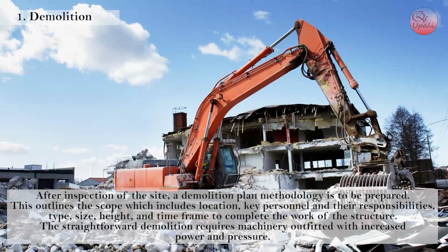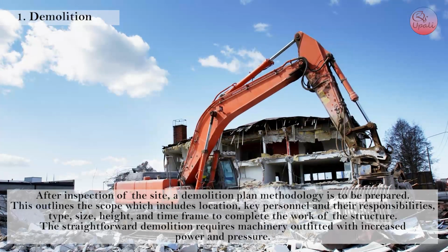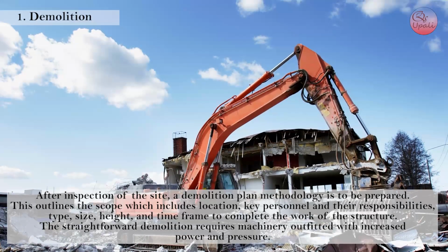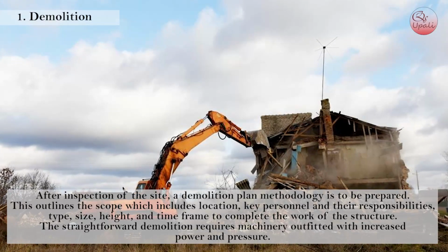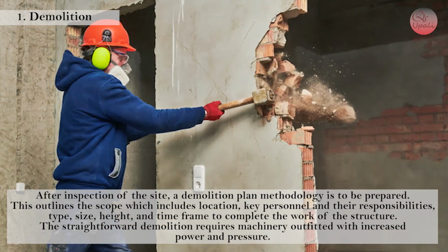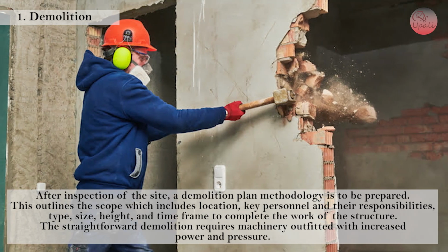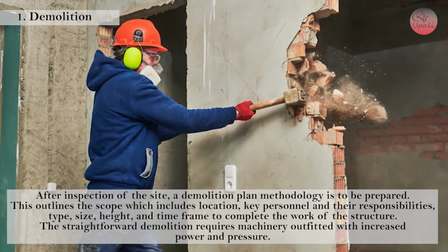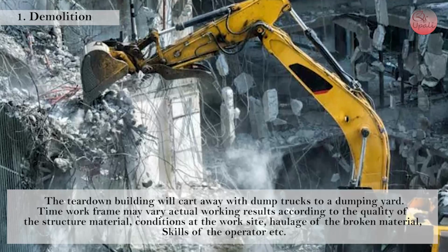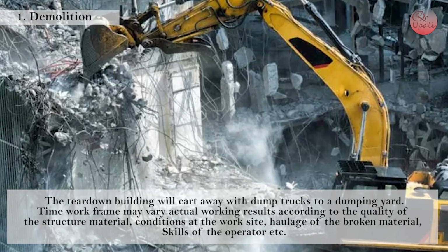1. Demolition. After inspection of the site, a demolition plan methodology is to be prepared. This outlines the scope, which includes location, key personnel and their responsibilities, type, size, height and time frame to complete the work of the structure. Straightforward demolition requires machinery outfitted with increased power and pressure. The torn-down building will be carted away with dump trucks to a dumping yard. Work time frame may vary.